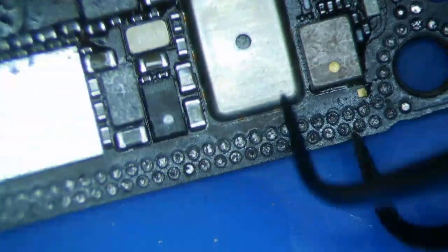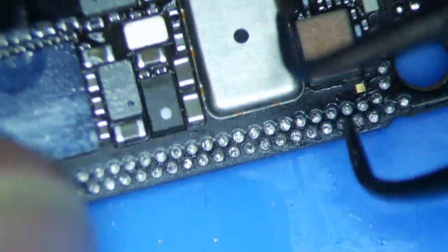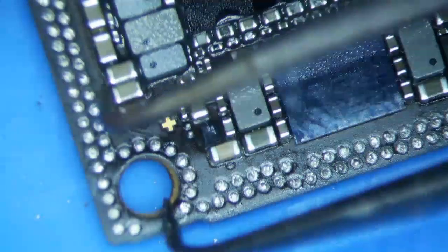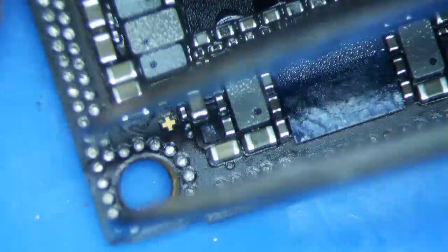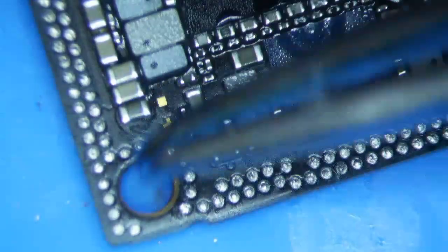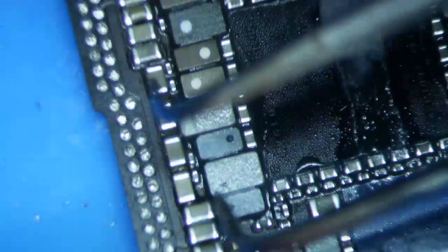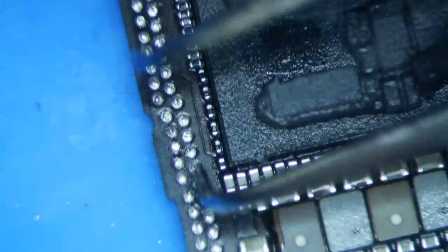Okay, so we're just going to go around the board, just make sure that there's a little bit of solder on each of these pads, just so that we can get a nice little joint. Re-sandwich, get a nice little re-sandwich. Okay, so let's see. I think it's good. I think this side is good. So my other side's been heating this whole time. Okay, so I'm just gonna bring it back here, and then same thing on this side.